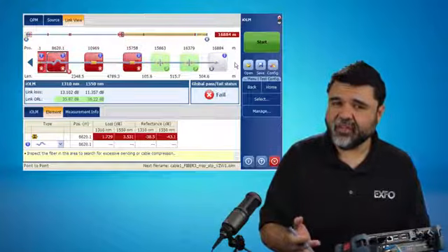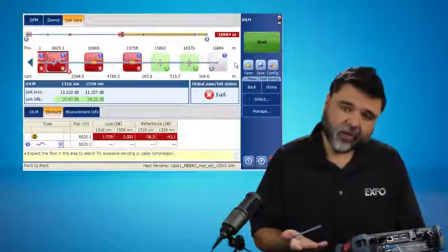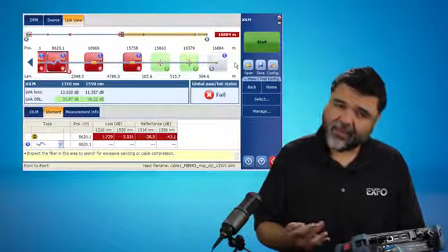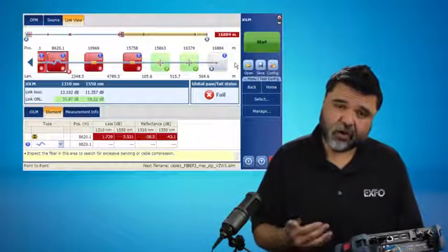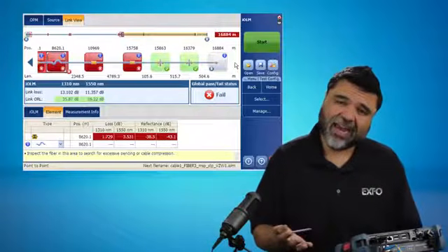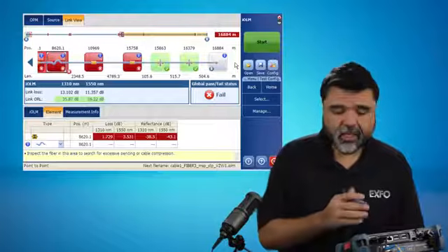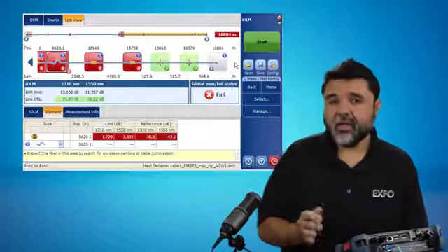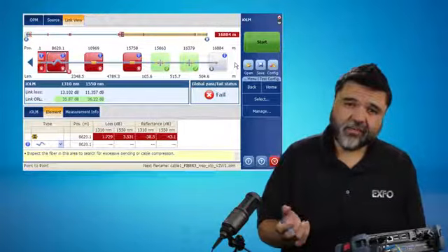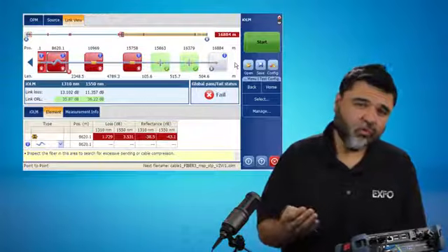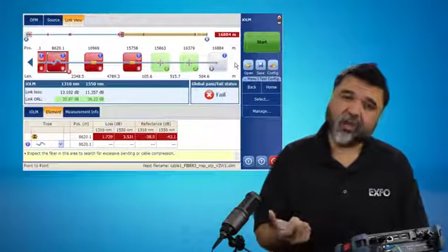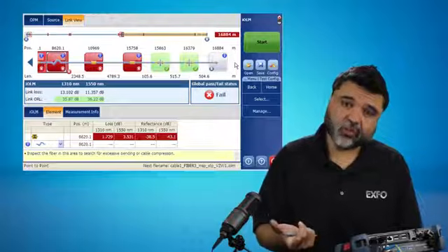And so the beauty of this is, when I worked disaster recovery, one of the biggest problems we had that extended our MTTR, our mean time to restore, mean time to repair, was fault isolation. By the time the technician got on site, ran the OTDR, isolated the fault, we were well into our 4 hours of our contractual MTTR to our customer.